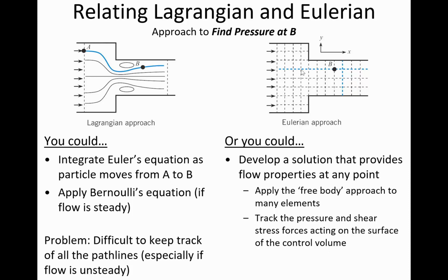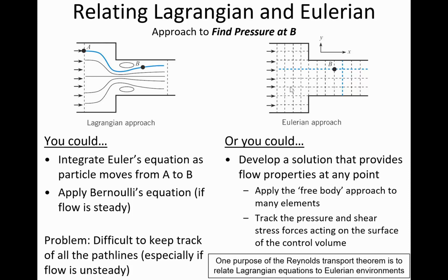So what we'd say is, what are the forces that are acting on just one of these boxes? The momentum that's flowing through it, the shear stress by the part interaction with the elements on either side of it. Because there would be fewer elements to track than each individual particle, we could let each cell represent essentially the fluid that was inside of it, and the characteristics of every particle inside of that mesh would be represented by the cell.